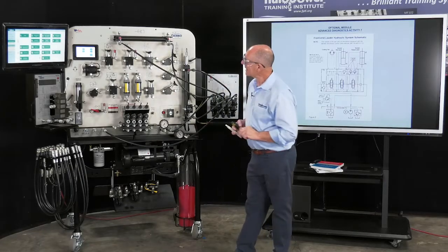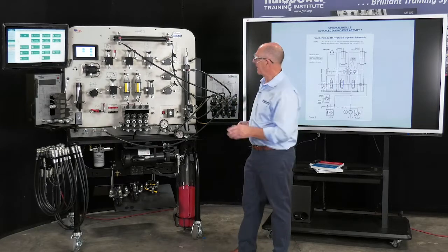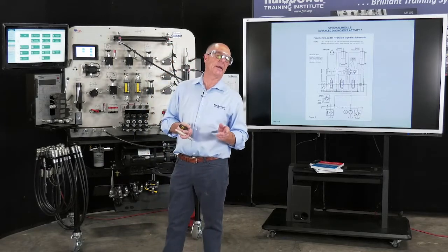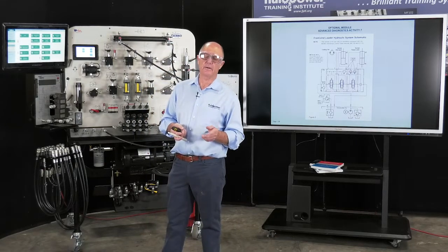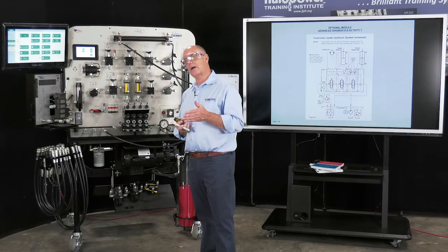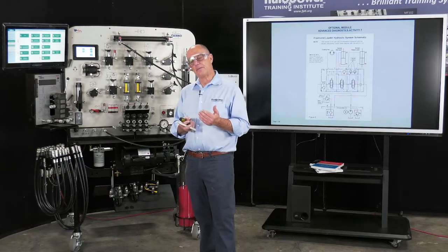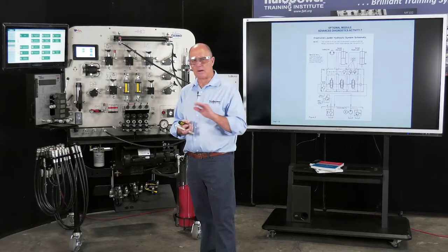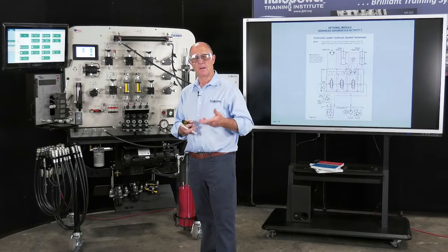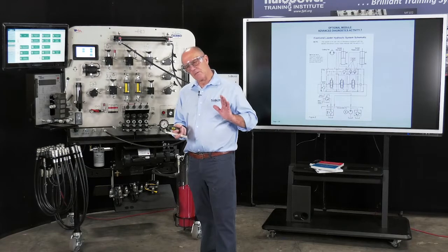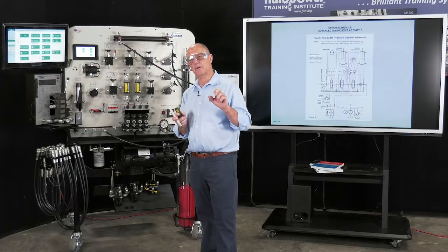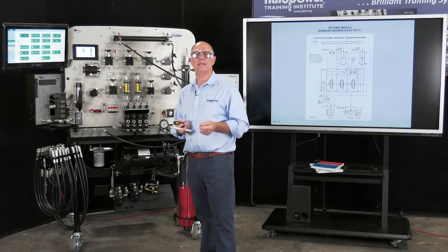All right. What I then did was find a way to test these components that's almost non-invasive. I started what you can call pressure decay, or what I call microleak testing. I found that if I pushed oil manually, it works; a power unit or some kind of portable power pump doesn't work. If I could manually push oil with a hand pump into a hydraulic valve, I could literally feel the leakage.